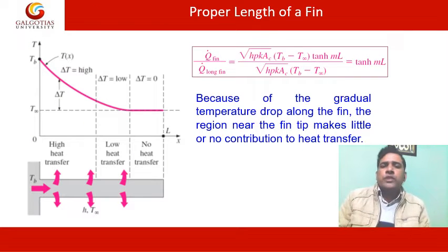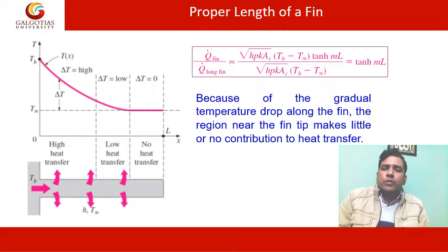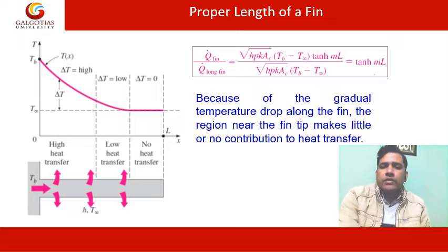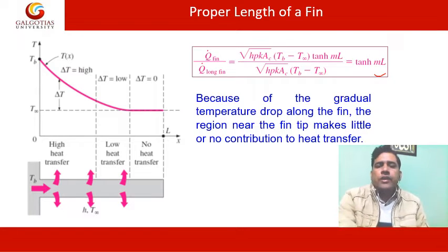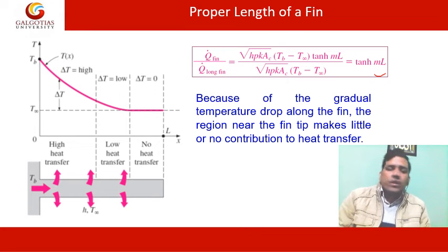Then what should be the proper length of a fin? The proper length of the fin should be such that it shouldn't be too short or too long. The proper length of the fin, as you can see, is given by this equation, and because of the gradual temperature drop across the fin, the region near the fin tip makes little or no contribution to the heat transfer.